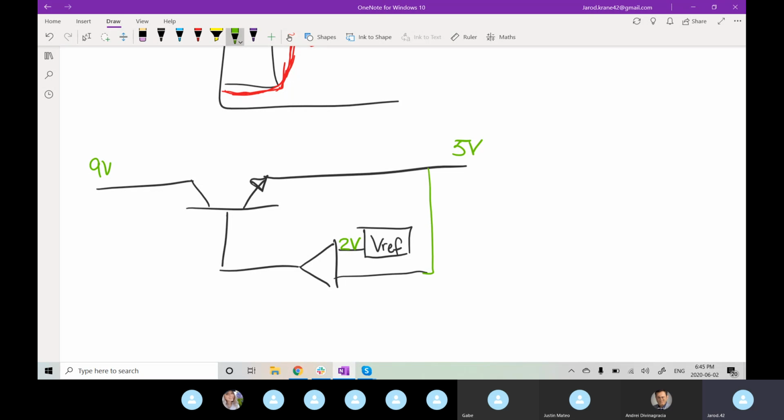Before, we would just tie it straight in, because if the ref was sitting at 5 volts and we're trying to draw the 2 inputs together, then obviously our negative pin is going to want to get up to 5 volts. But if our VREF is only 2 volts, by doing this short, all we're able to achieve is 2 volts on our output, which is undesired.